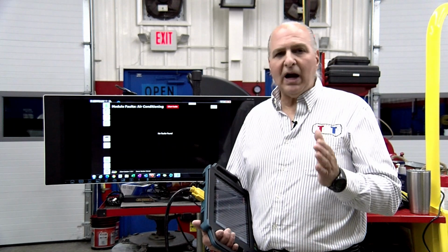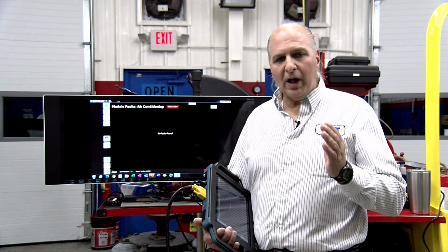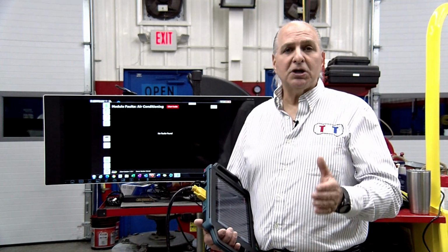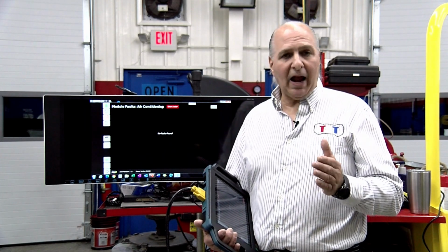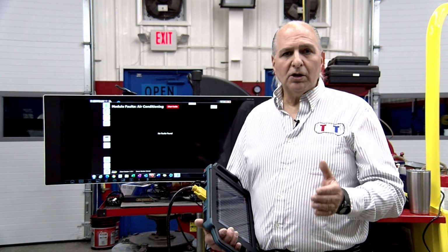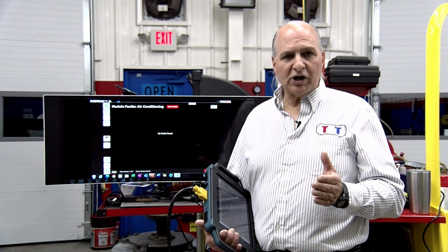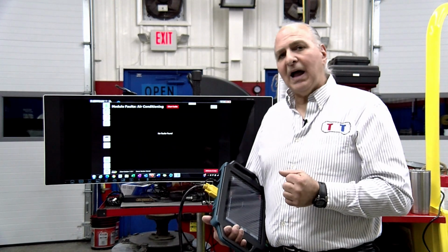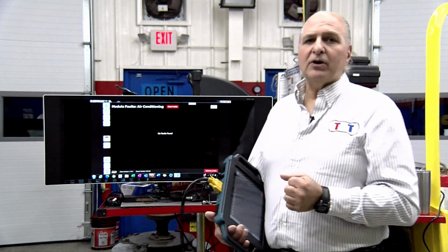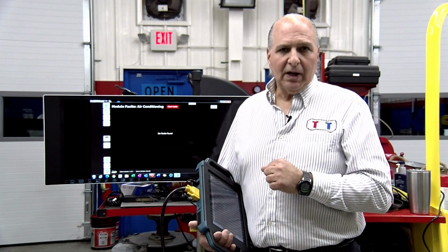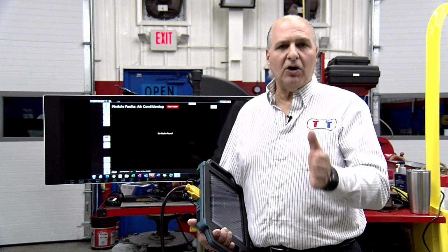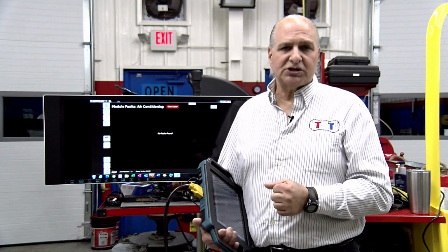And if you do not have the right equipment, if you don't have a line flush type of AC machine, if you don't have an air sep unit that can separate the PAG oil so you don't ruin that compressor, the problem with a lot of these vehicles that you'll run into is something called an isolation fault. An isolation fault can occur from someone doing an air conditioning service.